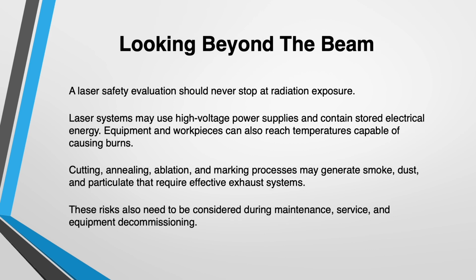A laser safety evaluation should never stop at radiation exposure. Laser systems may use high voltage power supplies and contain stored electrical energy. Equipment and workpieces can also reach temperatures capable of causing burns. Cutting, annealing, ablation, and marking processes may generate smoke, dust, and particulate that require effective exhaust systems. These risks also need to be considered during maintenance, service, and equipment decommissioning.